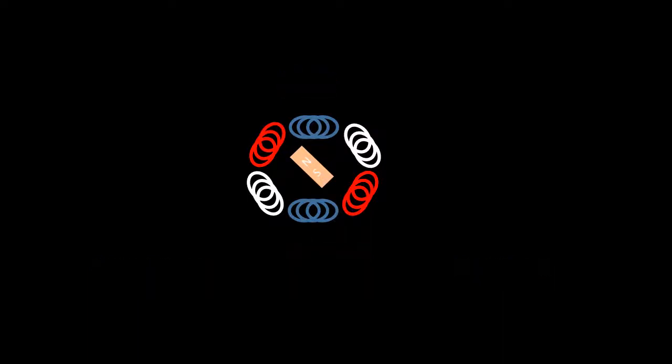In a three-phase, two-pole induction motor, you have three pairs of coils placed at 6 evenly spaced locations surrounding the rotor. Each coil pair is placed directly opposite each other. The electrical connections of each pole pair ensure that they always produce opposite magnetic polarity to each other. With even spacing, it works out that each coil pair gets positioned at 120 degree intervals around the full 360 degree rotation. The rotor gets pulled around by the constantly rotating magnetic field set up in the stator coils.